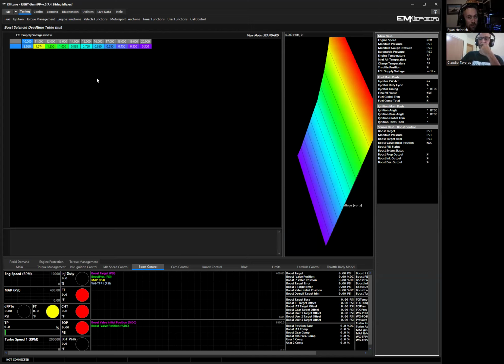So with voltage, like I'm saying, we're getting this dead time characterization for certain things. Then there's going to be these compensation tables, like air temperature, exhaust pressure, all this stuff. As much as you can bake into the back end to calculate for you and actually get you close, and then you can identify what your needs are, the better the vehicle is going to run day in, day out.